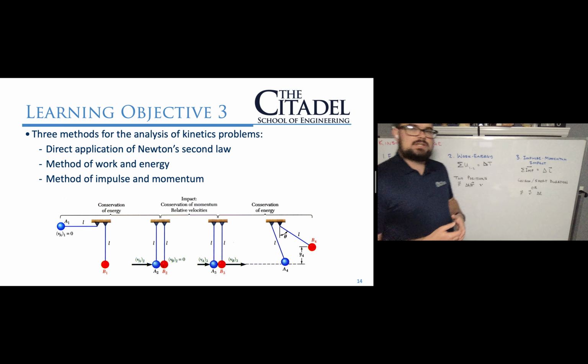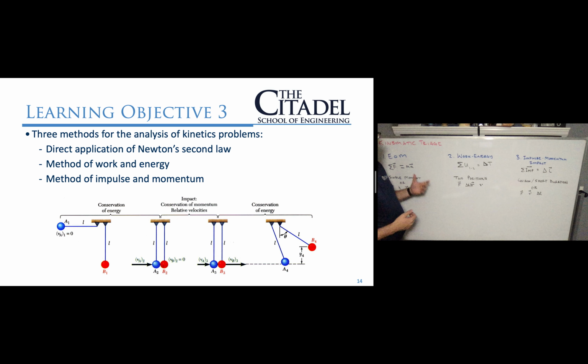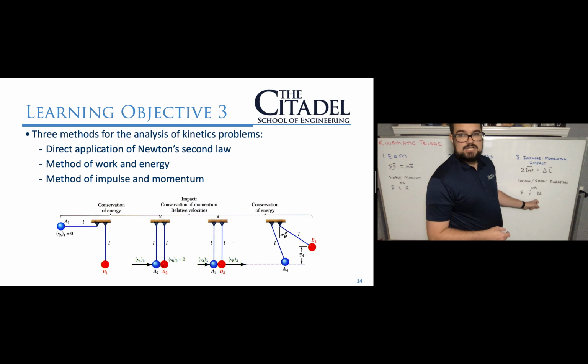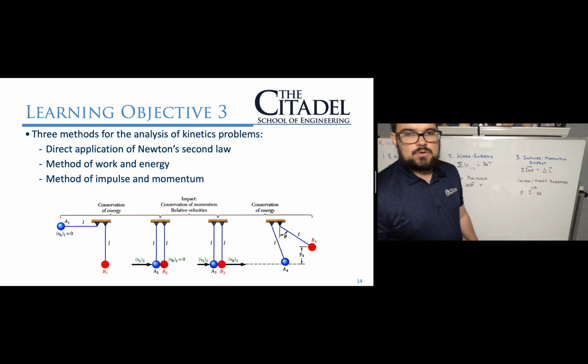And so we want to learn to be able to triage, to prioritize which tool we'd want to start with. And so if we're looking at a single moment, the equations of motion. If we're looking at a change in position, work energy, and if we're looking at a change in time or something of very short duration, impulse, momentum, and impact would be our tool.